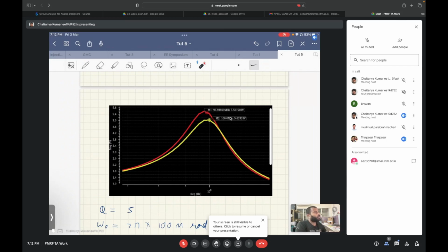For example, you want to design as many biquads as you want. Let's say the question was that you were supposed to design a sixth order Butterworth filter, and for that you did the equations. So let's say you want some more questions, so you can change the order to, let's say, 10, or maybe something else. For that you can decide the elements, do the dynamic range scaling, decide the order of the quality factors. So all these things you can do and verify it with simulator.